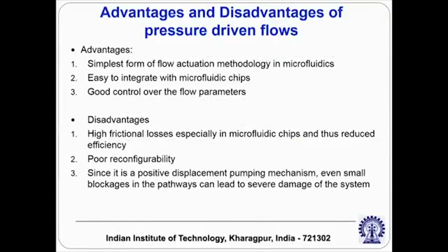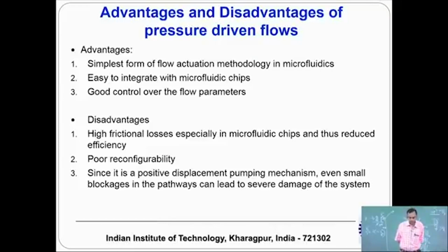So we will summarize the discussion in this lecture by pointing out the advantages and disadvantages of pressure driven flow. For that I will refer to the slide. The advantage of pressure driven flow is that it is the simplest flow actuation, right. You just need a syringe pump to drive the flow. It is very easy to integrate with microfluidic chips. Anybody who has started working in a microfluidics lab will know how to operate a syringe pump, and it can have a good control over the flow parameters.